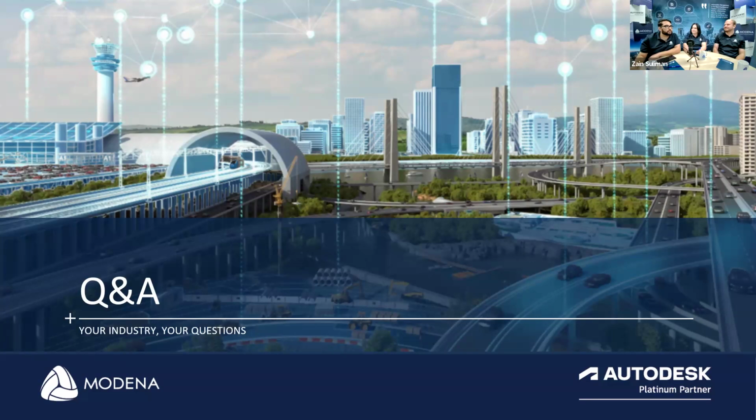So with that, what's important to remember is whatever you model inside of Revit gets created as an analytical link. When you do import it into Robot, you do want to modify your elements just so that they are basically how you would want to design them. So adding offsets, adding different gamma angles, adding different shortenings or anything, you would want to set that up so that if you want to do your calculation for your reinforcement, it will give you what you are currently looking for.